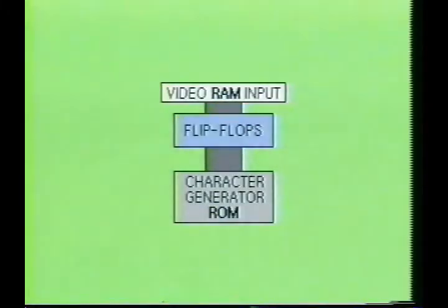As you recall, the video RAM was fed through a latching device into the character generator. The character generator is nothing more than a ROM coding device. It receives the 7-bit formatted data and outputs 7 scan lines of 5 dots each per character. If you were to magnify a single character section, you would notice that each character could be illustrated in this 5x7 block by simply turning on or off each point of light within the designated area.